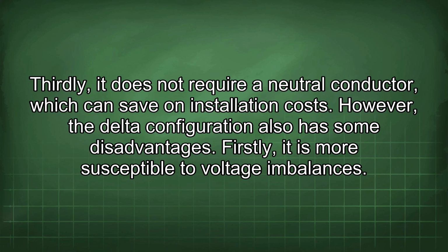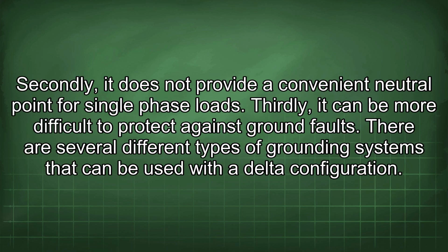However, the delta configuration also has some disadvantages. Firstly, it is more susceptible to voltage imbalances. Secondly, it does not provide a convenient neutral point for single-phase loads. Thirdly, it can be more difficult to protect against ground faults.